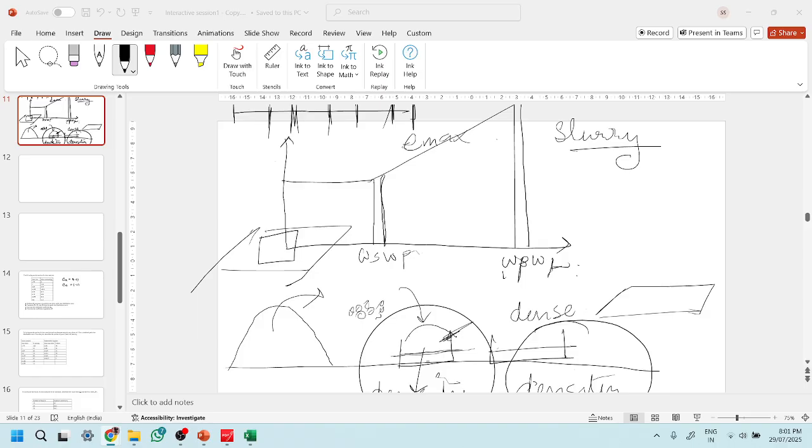Madam, in the professor's lecture in week 2 beginning, he discussed the phase diagram in detail, in which he mentioned the void ratio range is 0 to infinite. But he said it is theoretical. Where are we using that? Void ratio cannot be 0. Yeah, void ratio cannot be zero. At the same time, it cannot be infinite also. But you have to give a range, no? That's okay, madam. But without knowing which soil will have infinite void ratio, which soil will have a 0 void ratio, why do we have to discuss 0 to infinite? For example,